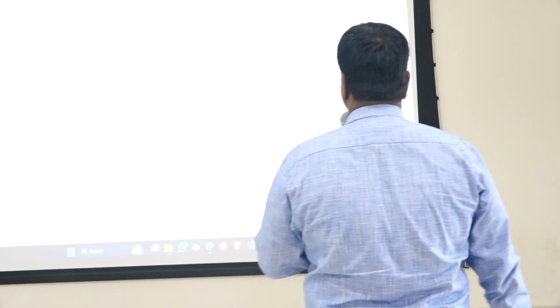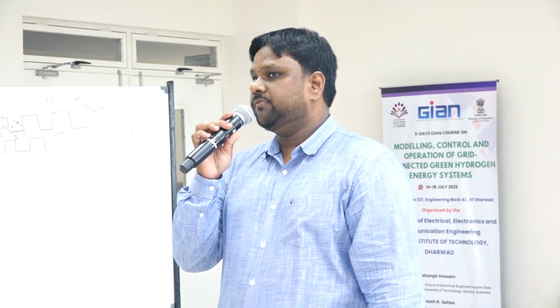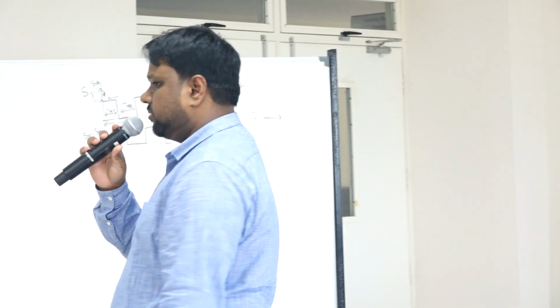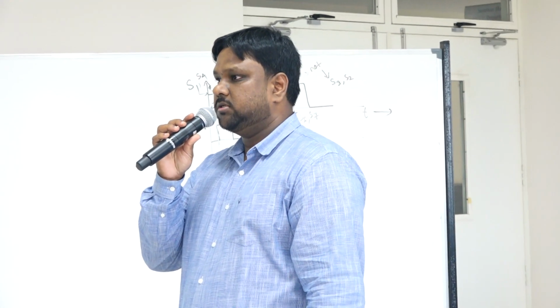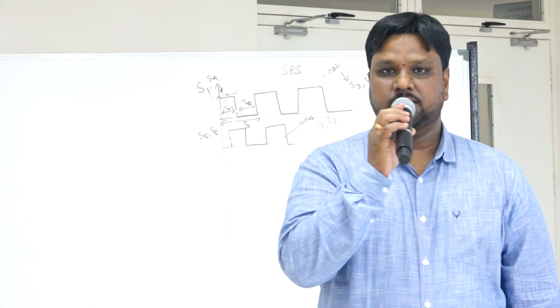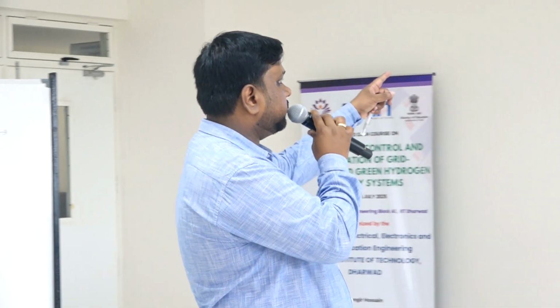Yes, sir. 8 pulses we are taking, 4 distinguished pulses. Okay, we will show S1, S5, S3 and S7. Signal input, give first signal as S1, second signal you give S5, third signal you give S3, fourth signal you give S6. Just put 4 inputs to the scope, run for 0.01 second. Run the simulation for 0.01 second.